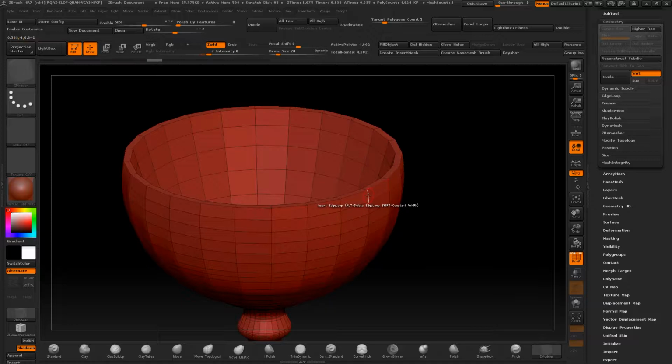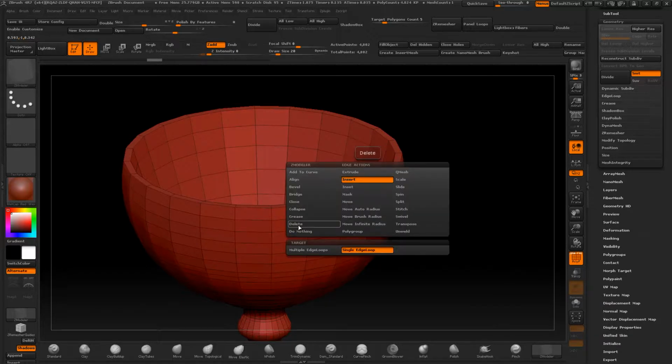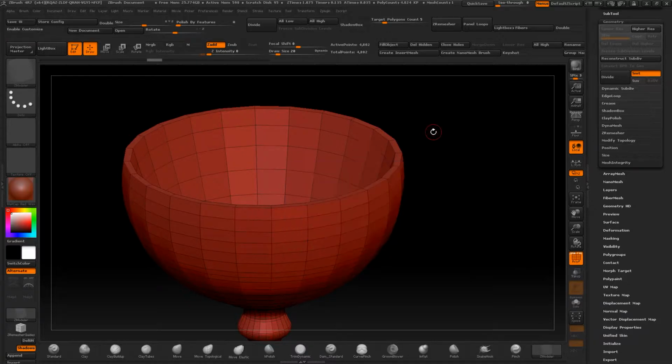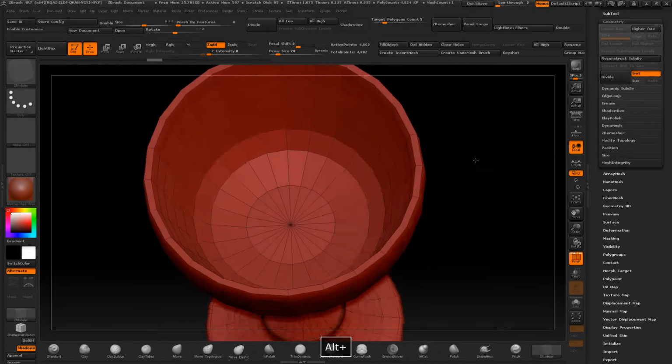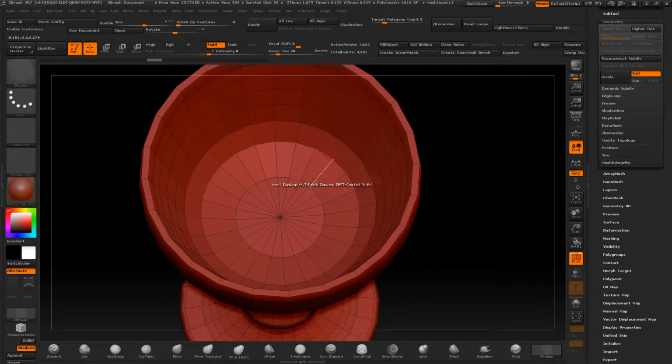Inside the edge, if I right click, we're going to get another square. This one is smaller, and here I've marked insert. Insert is so that we can insert cuts. We're going to be using this a lot. For example, maybe we want to cut here to add in some details. Well, we insert the cut.